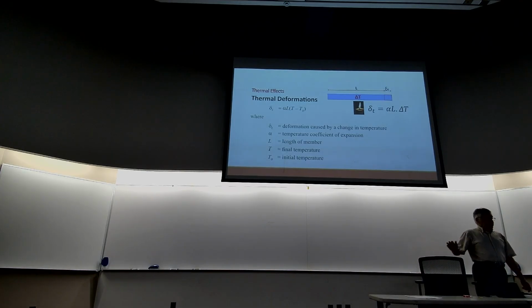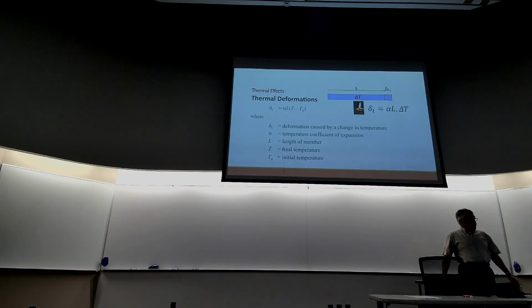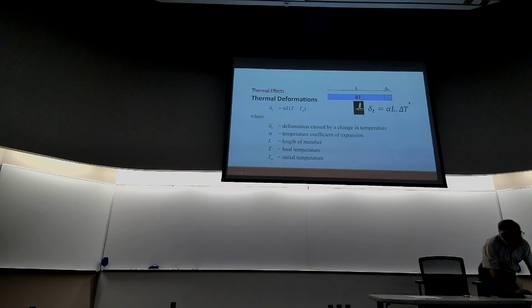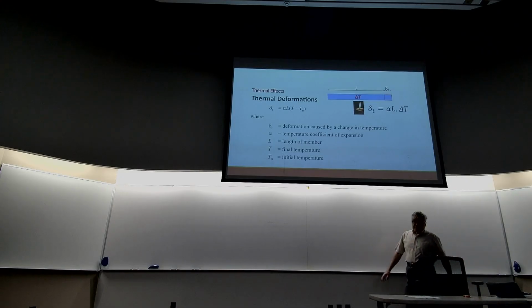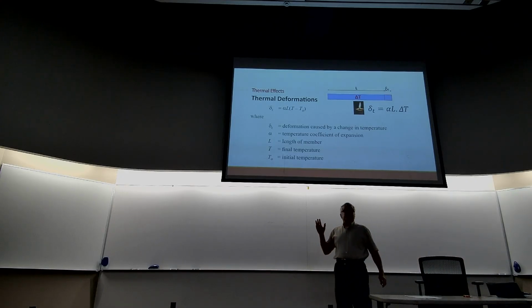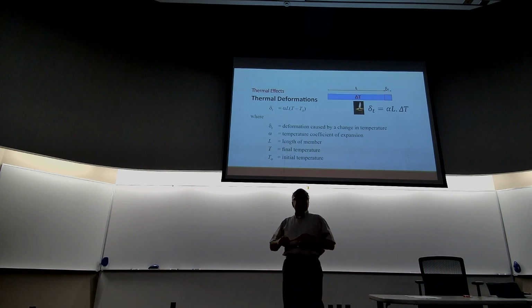And the elongation due to temperature change is shown by this simple equation in which alpha is the coefficient of thermal expansion, which comes out of our tables. L is the initial length, and this is the temperature change. Do you think there will be stresses developed in the material as a result of what we're doing here? Yes?